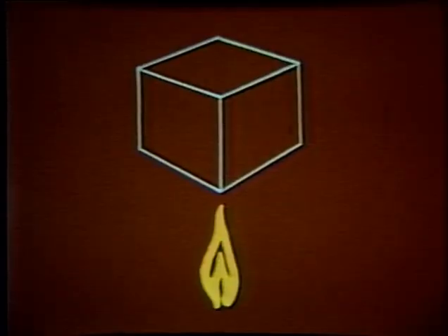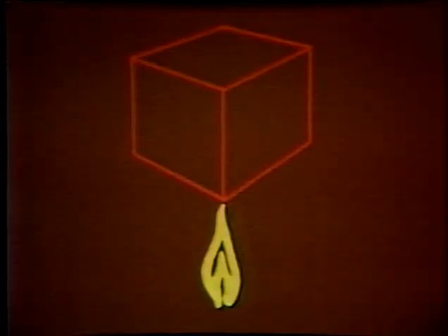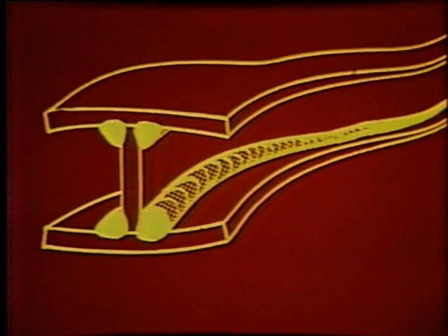When metal is heated, it expands in all directions. And when it cools, it contracts in all directions. It is the non-uniform heating and cooling of a weldment and the partial restraint resulting from the parts that cause distortion and warpage to occur.